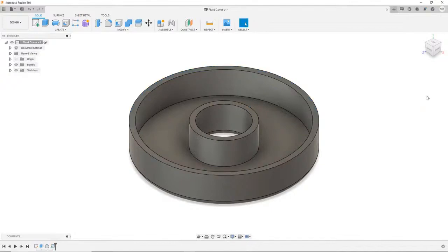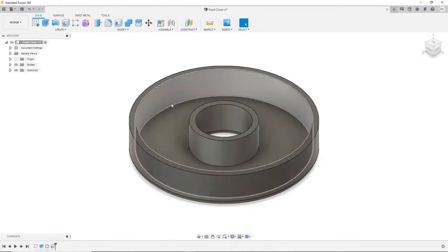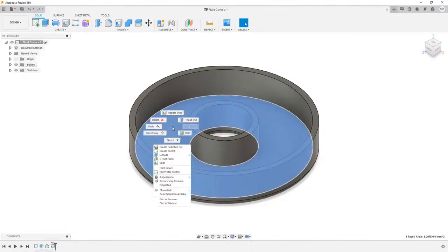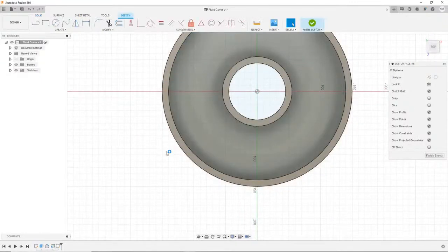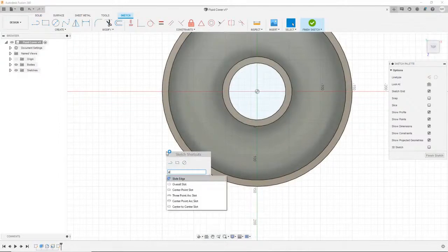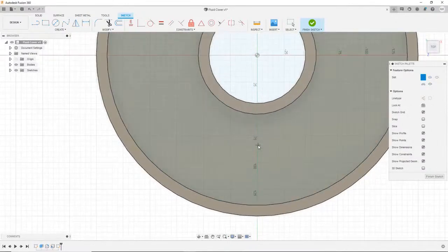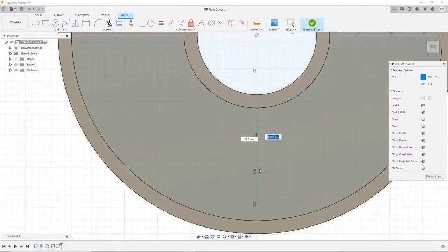Let's now create our sketch for cut extrusion. Let's create a sketch on this face. Left click, right click, and select Create Sketch. Pressing S for design shortcuts, typing SLO, selecting center to center slot. Let's place our slot here, zooming in, left click, and left click.